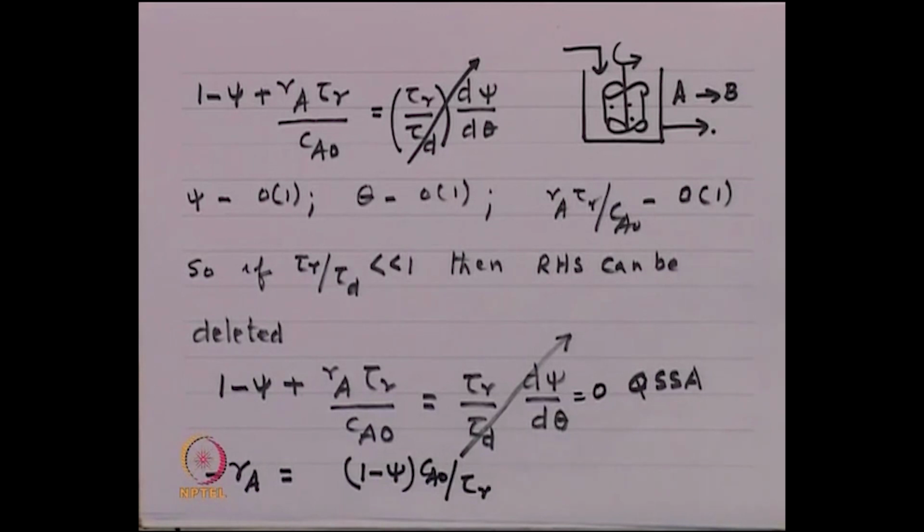So, what we are trying to say here is the following. Here is an instance of a reaction with a catalyst which undergoes deactivation, which means the reaction rates keep on changing because the catalyst is losing its activity. Our interest in this whole problem is to be able to measure this catalyst deactivation and quantitate this through a model.